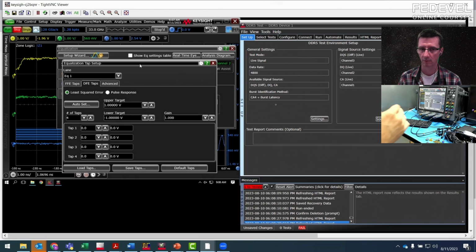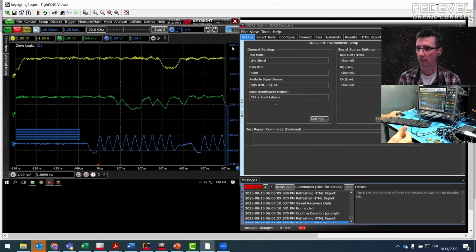And then it readjusts, and it does this back and forth until it finds the right DFE tap values. The taps are like weights. They're gain coefficients to boost the signal. And in that way, if the signal is small on certain bits and larger on others, it knows, based on the training, that I need to apply more gain to this one and don't touch this bit here. And that's the whole premise of equalization.